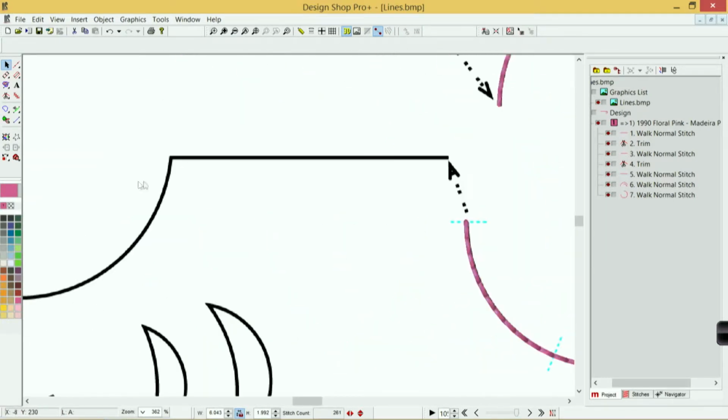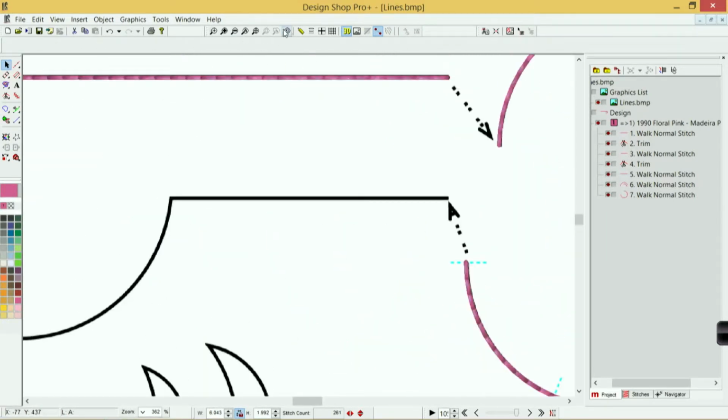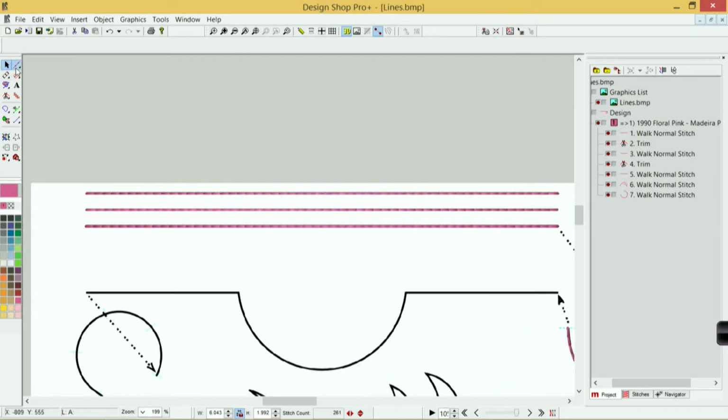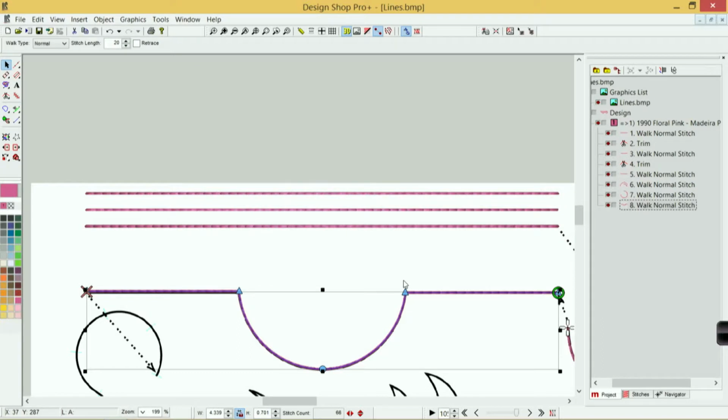Sometimes it would be easier to edit in a shape. If I move back over here, I could just digitize across this form. I could start with a left click, come across, left click, right click to bisect that curve, come up, left click, come across, left click, and hit enter to complete that shape. And that would work. But if I wanted to make sure that these two lines were absolutely even and completely parallel, it might actually be easier for me to edit in this curve.